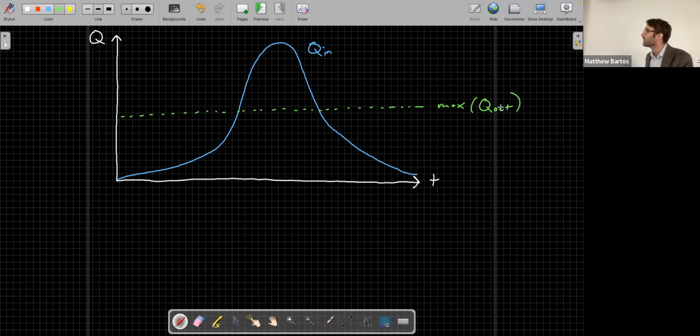Right. So if we try to use feedback control to essentially minimize the difference between H and href, basically by the time that the control starts to act, it'll be too late, because we can't let out enough water to prevent the pond from overflowing, right? What we really need to do in this case is plan out our control actions ahead of time. We need to release some water preemptively so that when the flood wave arrives, it doesn't overflow the reservoir.